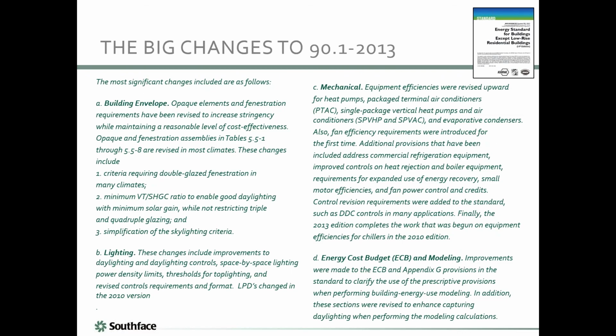In terms of the major changes between the 2007 version and the more current 2013 90.1, really not so many big changes. One of the big chunkier parts of the energy code is these tables and tables and tables of efficiency, and they're still there, and they've been updated, and they've included a few additional types of equipment. But it's basically saying you need this minimum SEER air conditioner or this minimum EER and so on, and most equipment you buy probably satisfies it, but a big chunk of the HVAC chapter is those tables.